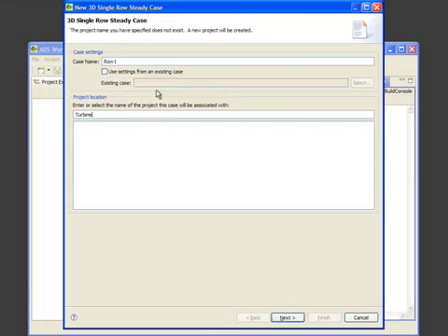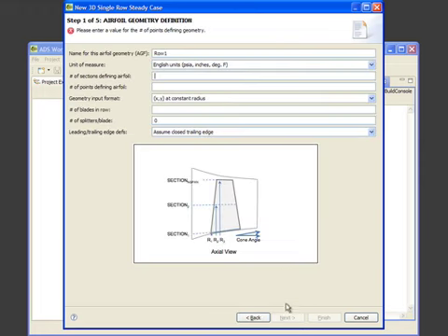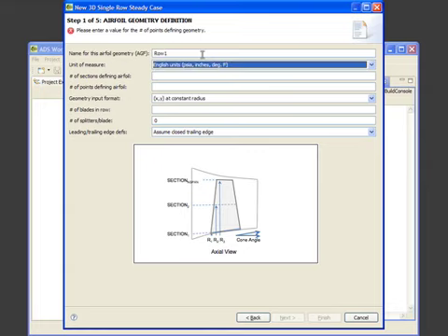So step 1 is to define the airfoil geometry data. The first thing here is the name of the AGF file. This is actually really important. Here, our AGF file will be called row1.agf. At the end of the wizard, all of our airfoil and aero and geometry data will be defined in the AGF file, so you do not necessarily have to open up the wizard again in order to get all the information for what was defined in your case.